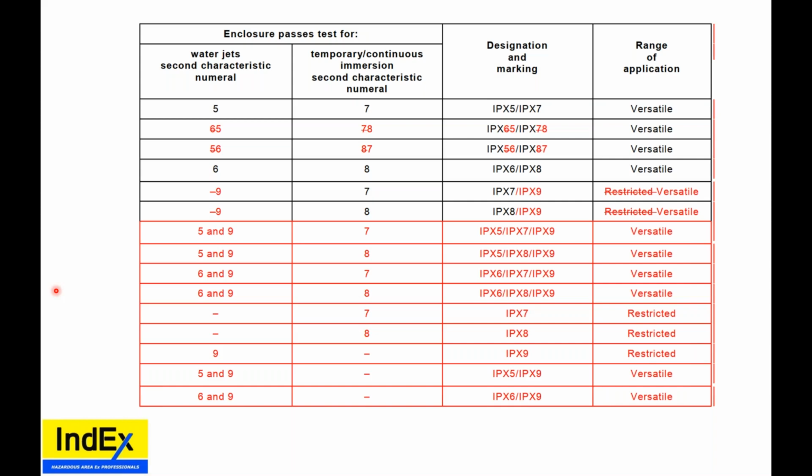if one of those documents or physical devices, the data sheet, the data plate, and the brochure, is lacking that information, by my own personal risk assessment, I would not accept it. There are errors within that manufacturer, or perhaps within that certification body or testing laboratory, and I would be apprehensive to accept that equipment. We have found within Australia, a certain manufacturer of LED lights has gone out of business because they did not meet their IP66 rating, and now it's costing end users millions upon millions of dollars to change out all those lights.